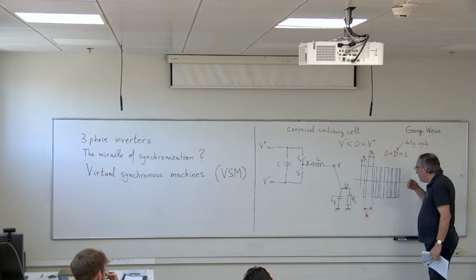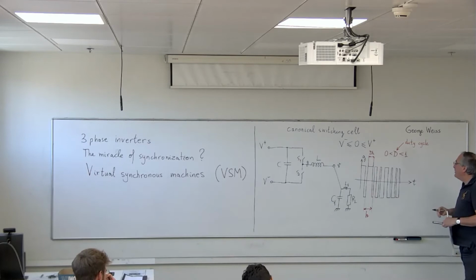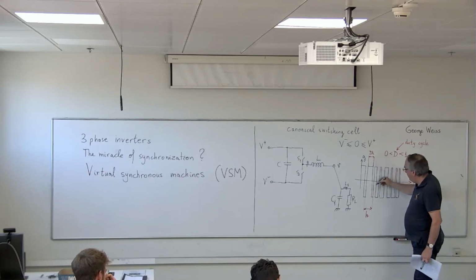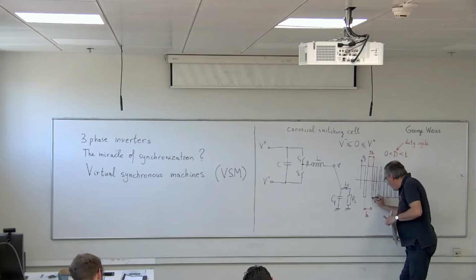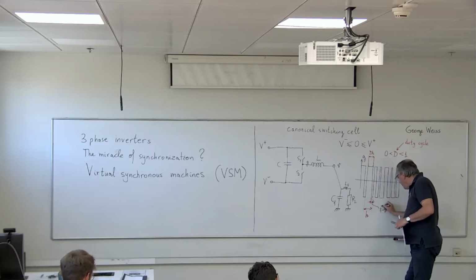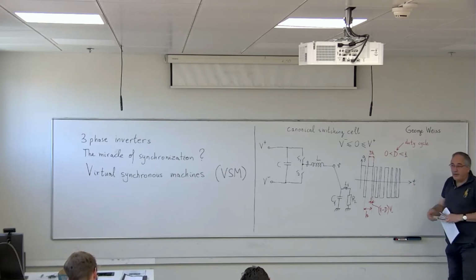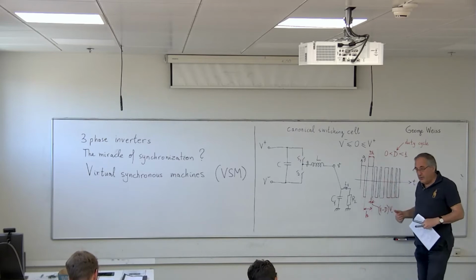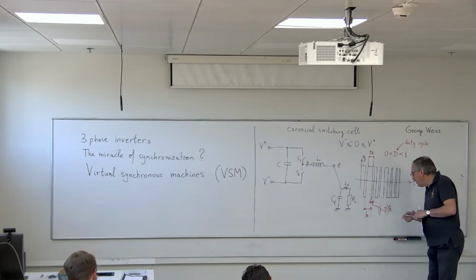And let me also mention here that this could also be equal to 0. Okay. And the time that the switch will be in the opposite position, meaning at V minus, when the point G is connected to V minus, will be 1 minus D times H. Sorry, I said V minus, but it should be times H. The time is (1 minus D) times H. Yes, that's what you wanted to say.